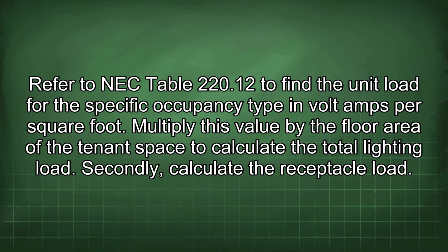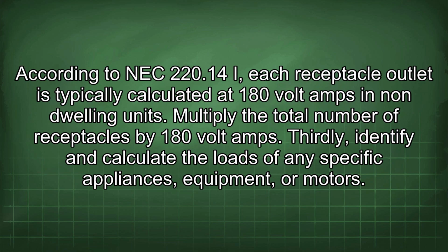Secondly, calculate the receptacle load. According to NEC 220.14(I), each receptacle outlet is typically calculated at 180 volt amps in non-dwelling units. Multiply the total number of receptacles by 180 volt amps.